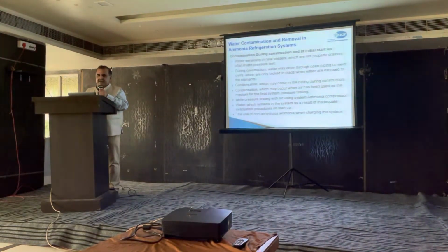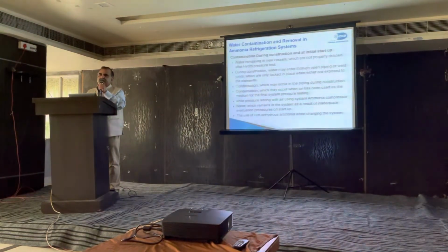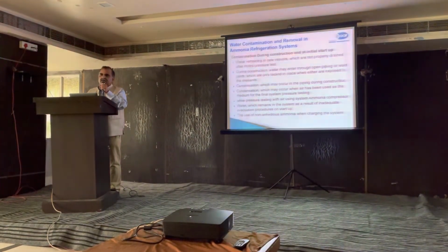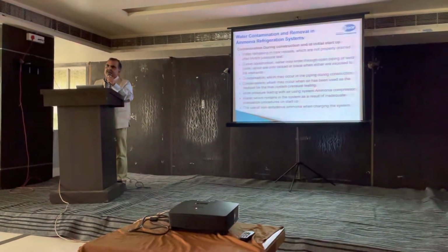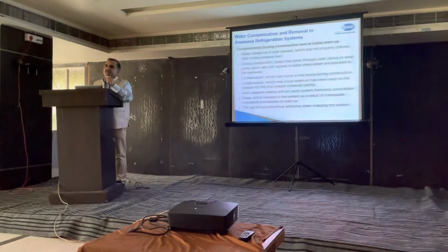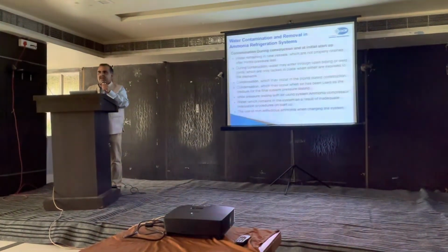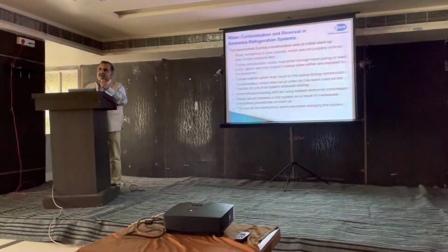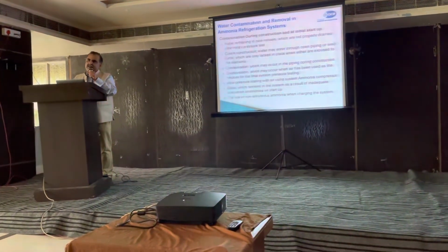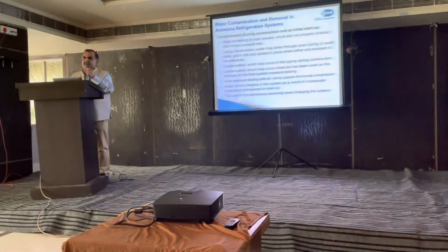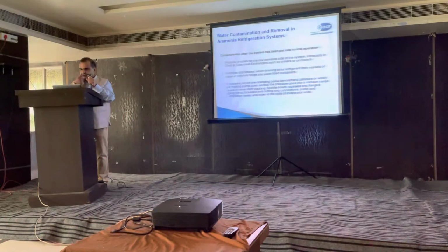The third point I am telling you: when you are buying ammonia, unfortunately we do not get purity certificates. Our vendors do not give them, we do not insist on a purity certificate, and they do not issue one. So the ammonia may contain water itself. As I told you, when we keep the ammonia cylinders at 180 degrees, if there is water in those cylinders, it will come into the plant.